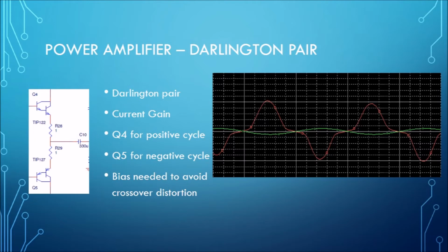This output resistance that I talked about comes from the parallel combination of the resistance into each Darlington that each of the emitters see, plus the small resistance added by the degeneration resistors. A small word on the degeneration resistors themselves. The reason to use these degeneration resistors is that they add a small negative feedback component to the temperature dependence of the BJTs. This is needed because this helps counter any thermal runaway effects that BJTs can go through.